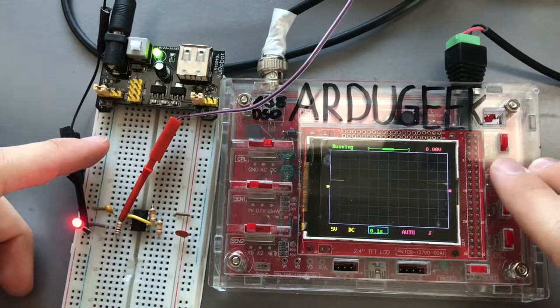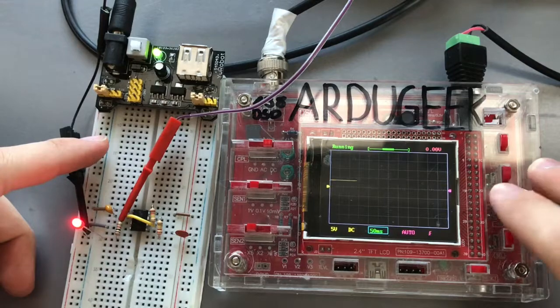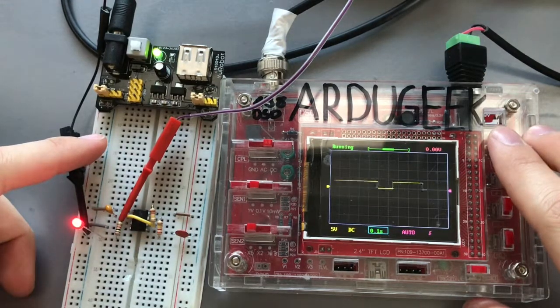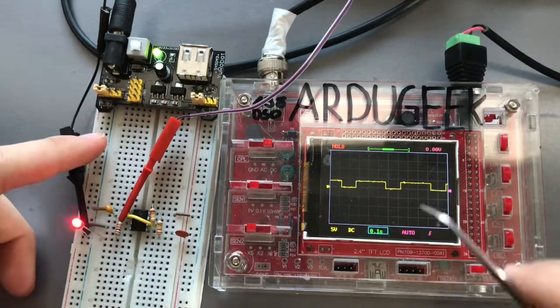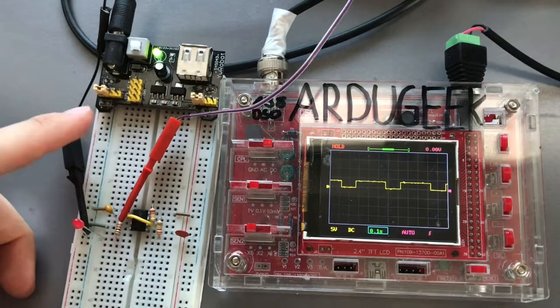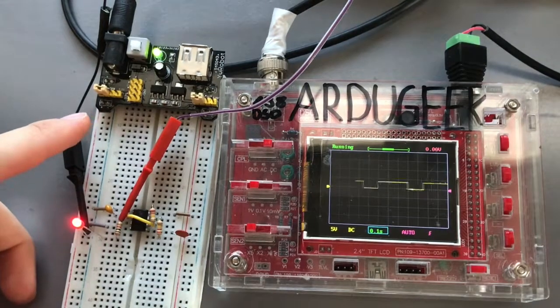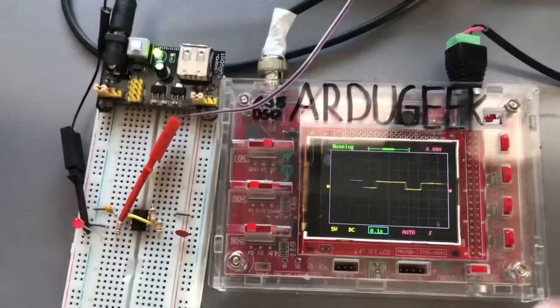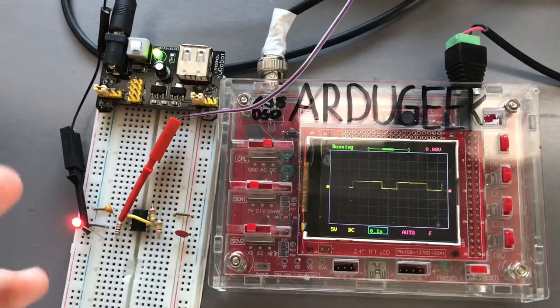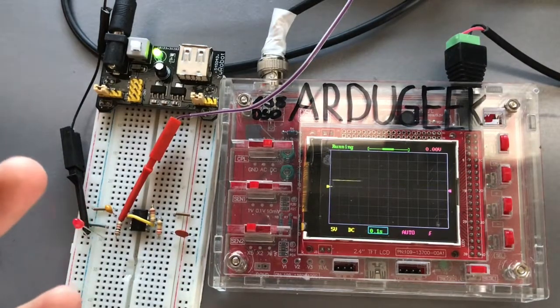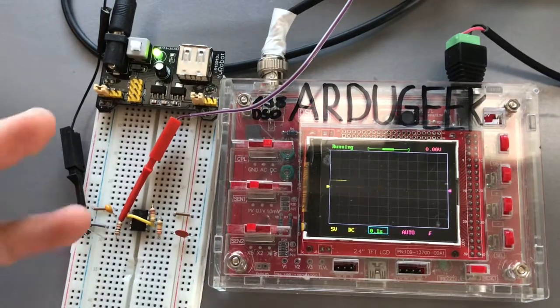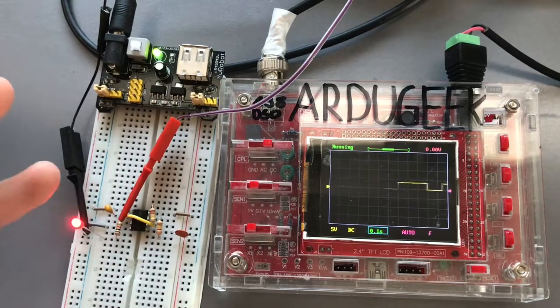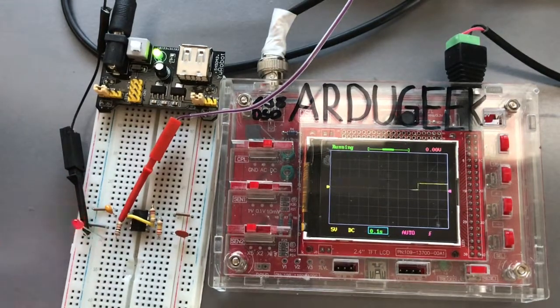Now we can increase the speed of the time base, and we will be able to measure the single cycle, which is roughly 0.3 seconds. So this is mainly the astable multivibrator, a pretty simple configuration of the 555 timer. You can use it for virtually anything. After the presentation I will show you some practical examples.